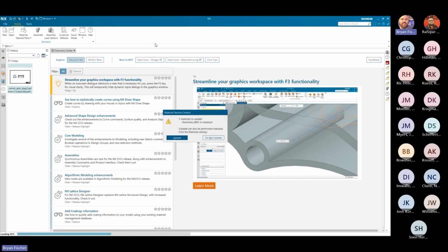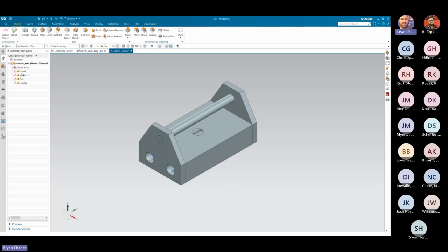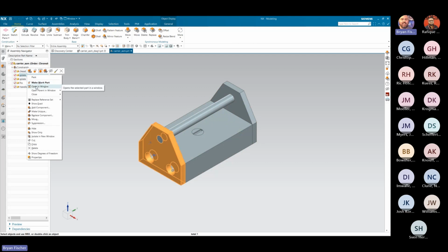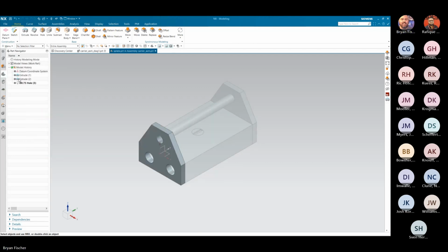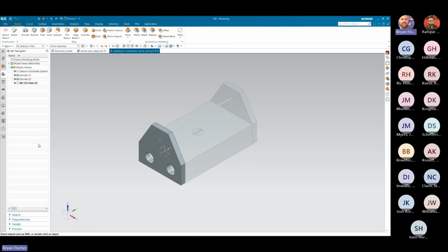Go ahead and open my drawing again. And this time, you notice everything's fully loaded. So if I come in here in my assembly again and make that change on this part, if I've done it correctly and I have everything fully loaded this time, we will be able to just make this change, and my wave geometry should update with it. That's why my recommendation is to always have it fully loaded or fully loaded lightweight if you're working with wave geometry.